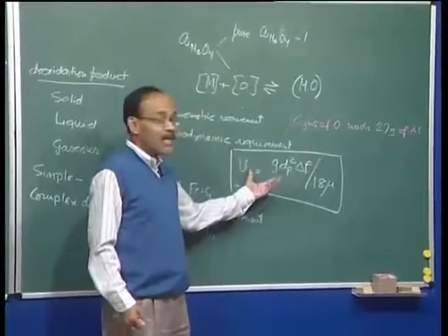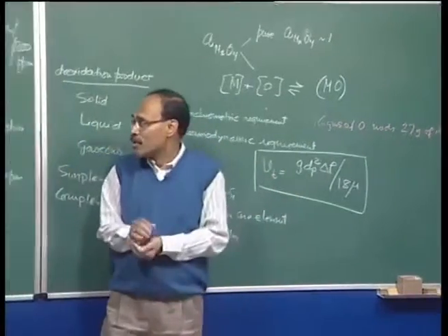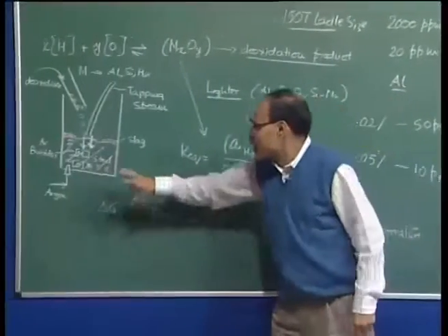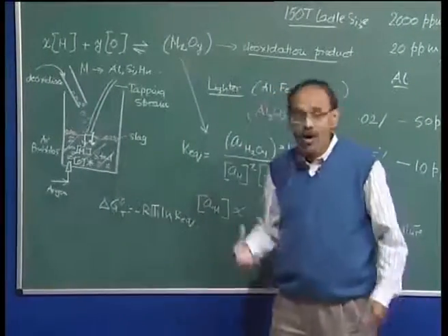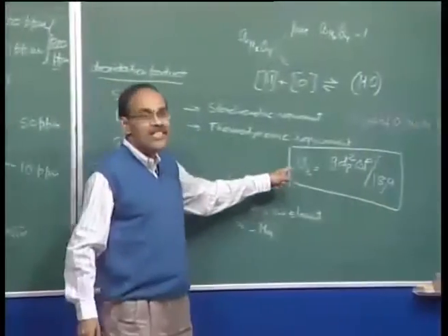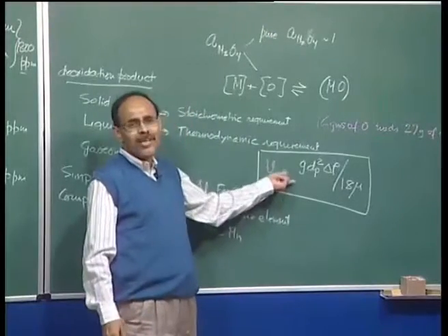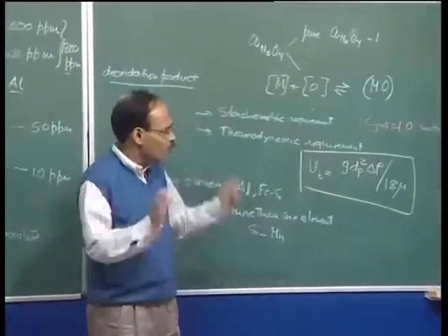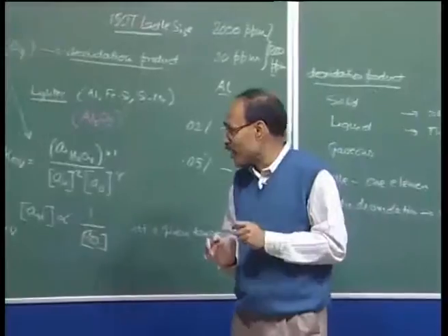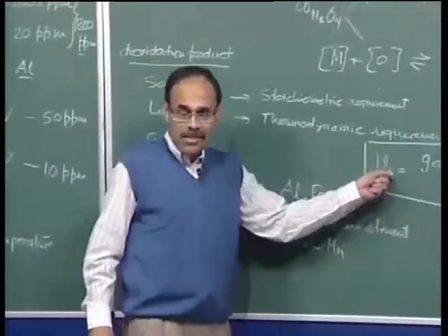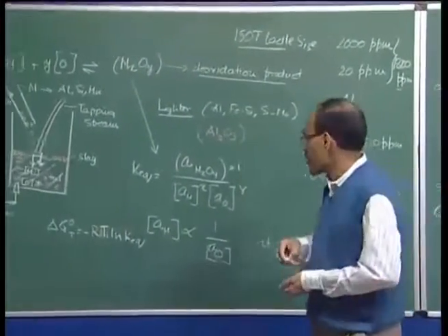Of course, Stokes law is a very simple law. We all know that it is valid for laminar flow, even Reynolds number of the order of 1, which is typically a very weak flow. And in this particular system, we know that there is fluid motion also. It is not the particle rising through a stagnant bath. Also, the surface tension in high temperature systems is different. The particles may completely wet, or may not wet. So this is an approximate order of magnitude calculation. These need not be taken too seriously. We just get some idea of what size of inclusion can float and what size cannot float, and nothing beyond that. No serious process design calculations or inferences should be drawn on the basis of the Stokes law as far as inclusion flotation is concerned.